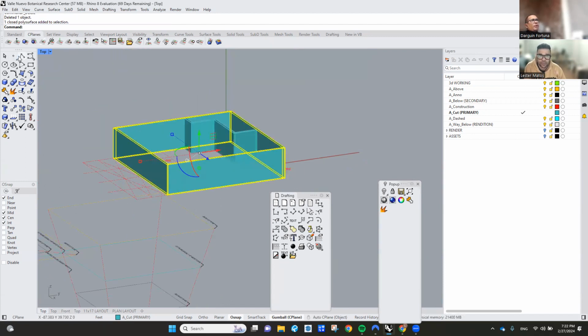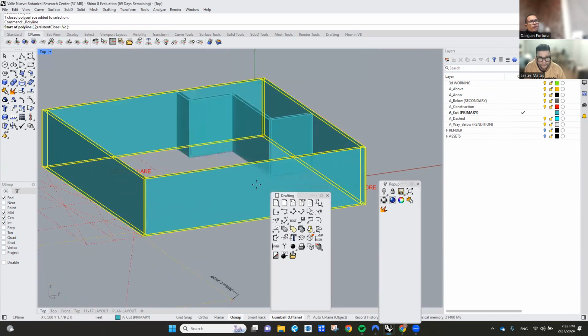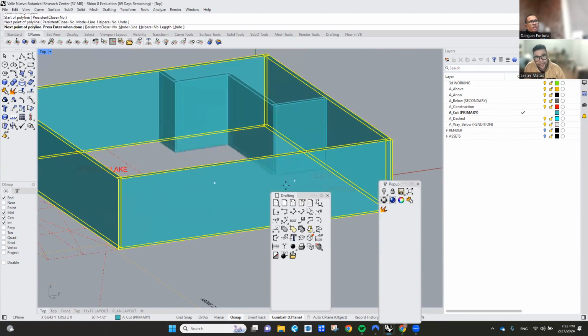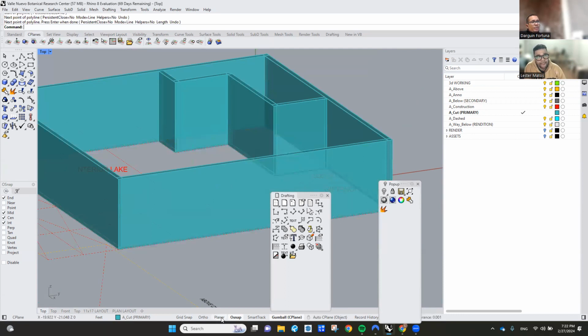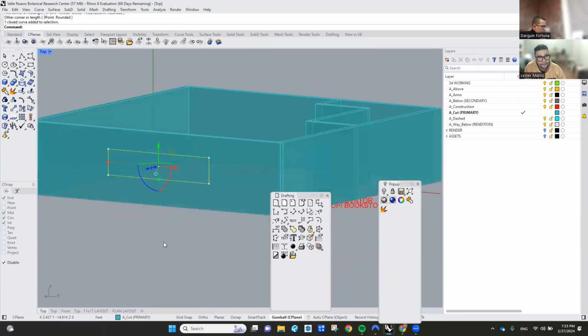And then I'm going to make an example in 3D of drawing something bizarrely up. Just make sure that your snap doesn't get in your way. So I would turn the snap off so that it doesn't mess things up. I would do a nice little rectangle, kind of where I wanted to go. Here it is. That's my window. And then I'm going to do extrude.